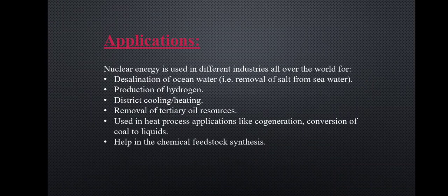Let's see the maintenance procedure of a nuclear power plant. The maintenance procedure includes two types: preventive maintenance and corrective maintenance. Preventive maintenance is also classified into three types: periodic, predictive, and planned. In periodic maintenance, time based servicing, part replacement, or overhaul, including periodic inspection and lifetime replacement, are included.